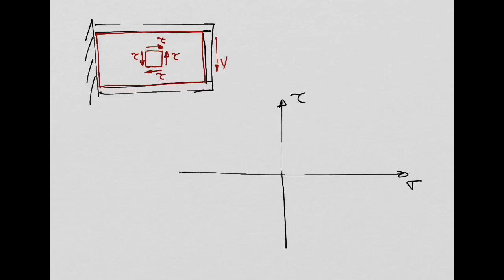How can I represent this pure shear in the Mohr's Circle? Well, it's a circle with the center at the origin of this coordinate axis, okay? Of this reference frame. So you have this circle here, it is your Mohr's Circle. So remember that this point and this point is where you have your shear stress tau from here, yeah?